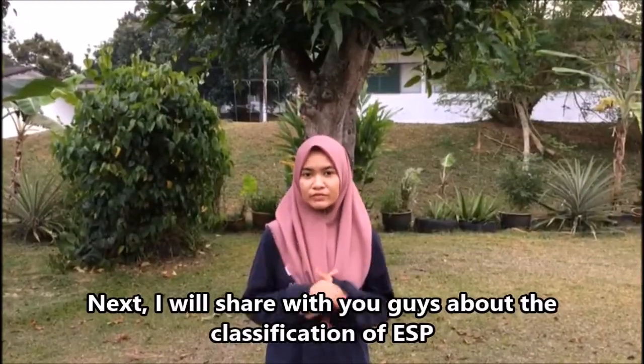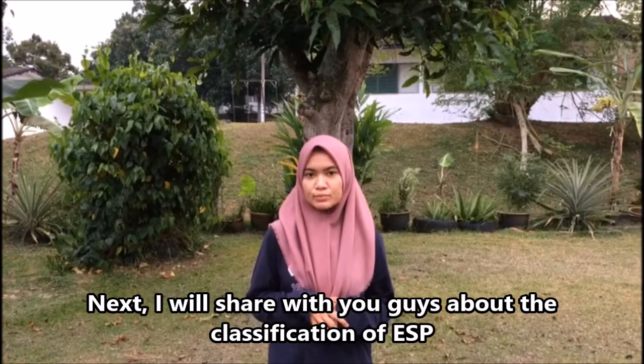Next, I will share with you guys about the classification of ESP. There are 4 classifications of ESP. First, the structural design and operation of discharge electrode and collection electrode. Second, the method of charging. The method of charging will be divided into 2, which is single stage and 2 stage. For single stage, the charging and collection will occur at the same time, but for the 2 stage, the charging and collection will be in different compartments.